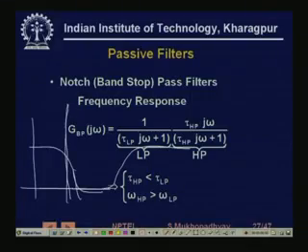what will happen is that at the low frequencies, this low pass filter channel will pass. So the signal will pass in the low frequencies. At the high frequencies, since the filters are in parallel, the high frequency channel will pass the signal. But in between, since both gains are 0, none of the channels will pass, and you have what is known as a band stop filter.